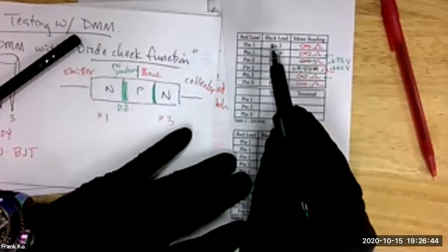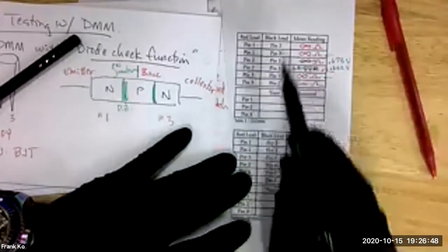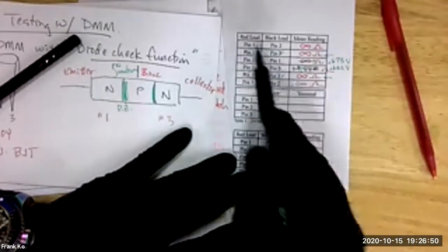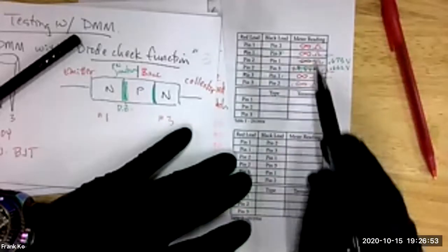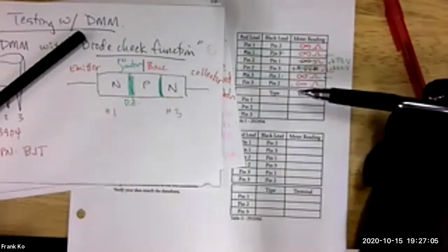This is a 1, 2 giving you infinity. This is a 2, 3. So there's 3 separate pins here. So this combination are not your outside pins. Only this row and this row are your outside pins. So we've identified the outside pins as being 1 and 3 because they give you infinity and infinity.